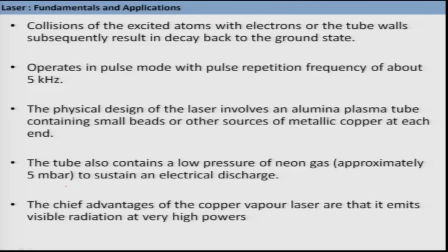How do you design this laser? The physical design involves an alumina plasma tube containing small flecks of metallic copper, and this tube also contains low pressure neon gas, kept at approximately 5 millibar, which helps to sustain the electrical discharge.